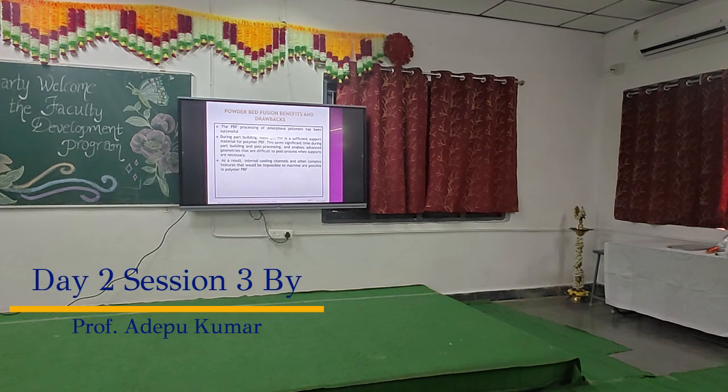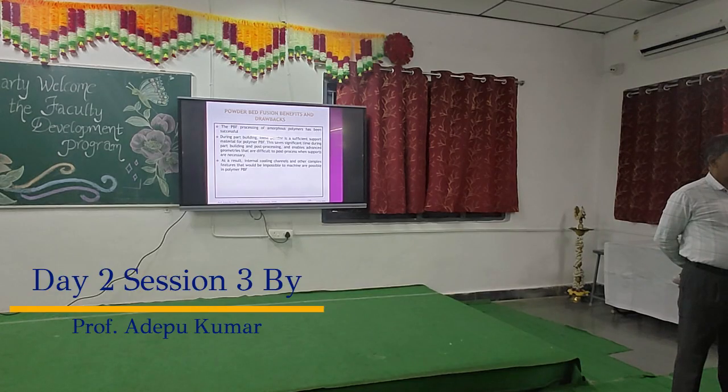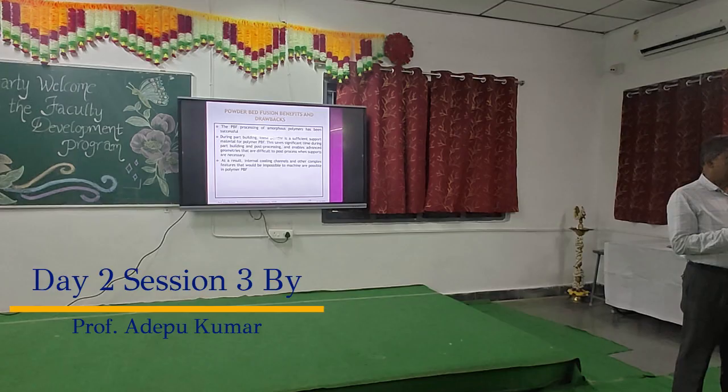For adding dissimilar materials, that is welding. So what are the properties that we need to consider? First of all, what I said is intermetallic components play a very important role. For example, aluminium and steel, or aluminum and copper. Al to Cu is an example I have given. First, you need to identify what phases are formed in welding of dissimilar materials. Then you need to know each phase's properties. Once you know the properties, only then can you see which phases to eliminate by using some alternative process or alternative techniques.